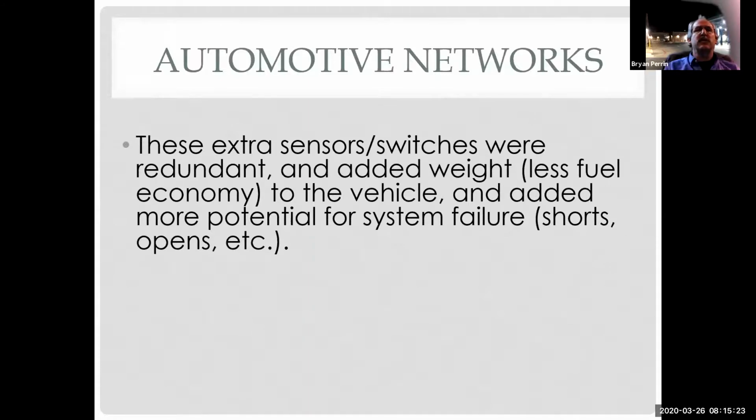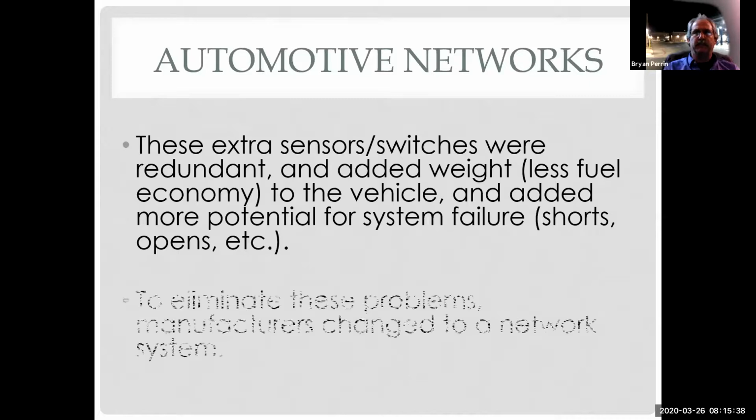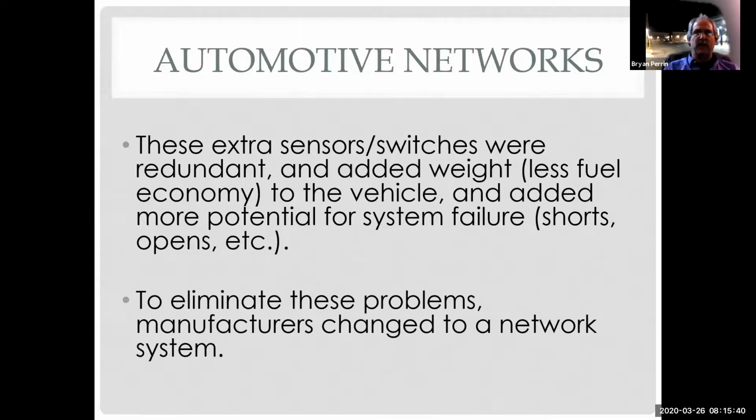These extra sensor switches were redundant, added weight, which meant less fuel economy, and added more potential for system failures because of more connections. The more connections you have, the more connections are going to go bad. To eliminate these problems, manufacturers changed to a network system.